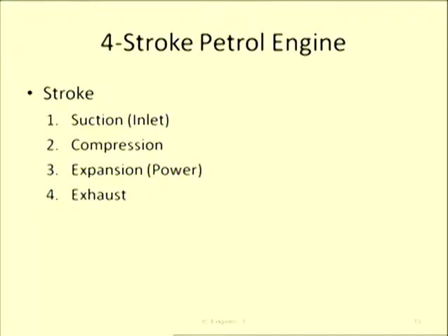Now, after reaching bottom dead center, the fourth stroke is the exhaust stroke. Now the piston will move up, the exhaust valve should open, so the exhaust valve will open, the piston is moving up, so flue gases will go into the atmosphere. So these are the four strokes.